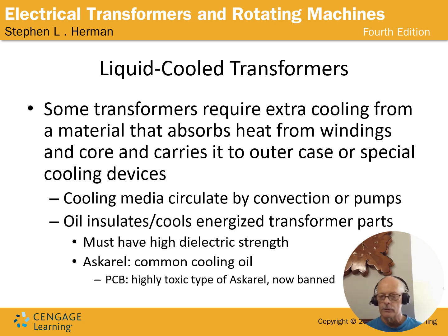It's using convection through the metal housing to carry the heat to the outside ambient air and carry that heat off. And so the oil gets cooled on a separate part of its cycle. It heats up and rises, it circles over, and it cools down and falls. And that circulation will get going and will continue to maintain itself by convection, right?